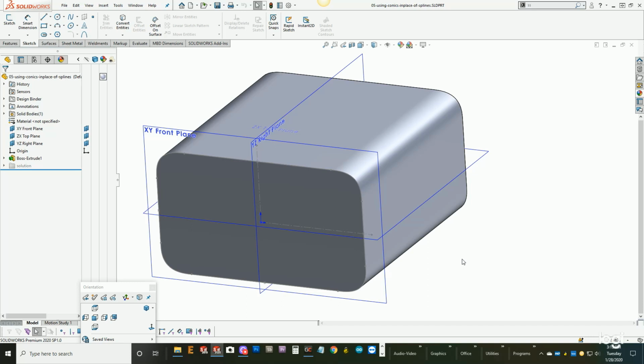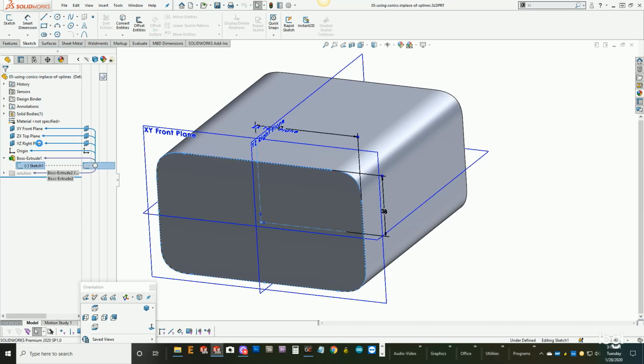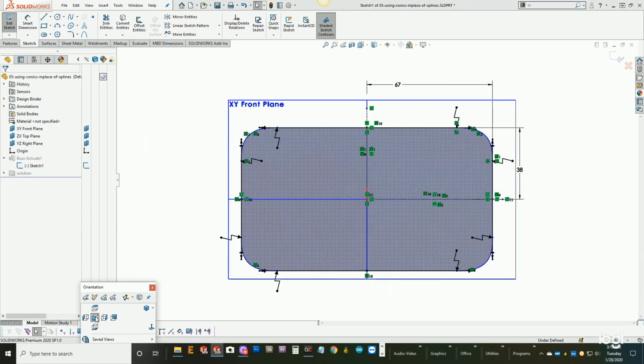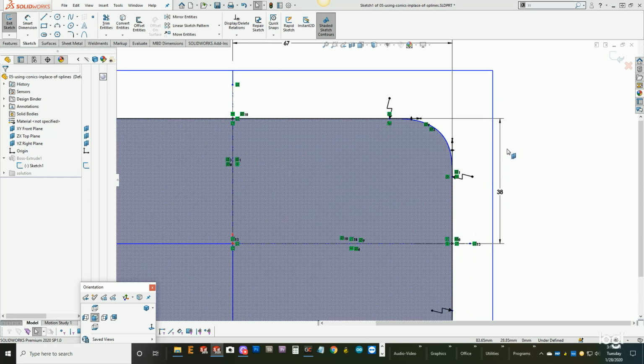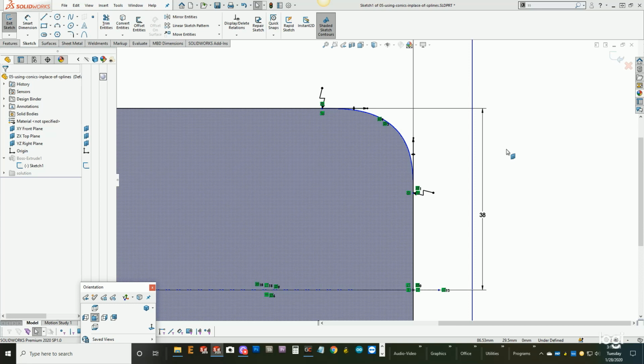So one thing I like to educate the industrial designers on is that oftentimes it's not necessary to have it C2, but there's ways to do robust modeling and still have C2, but also have robust features and editable features. So one of the things that I do is oftentimes I will introduce them to Conics, which are a way of getting C2, not technically, but it gives you basically the same effect.